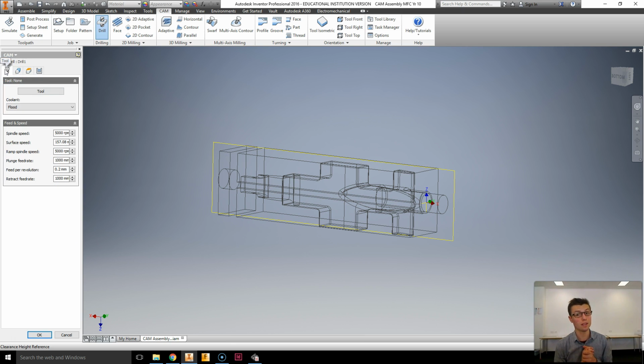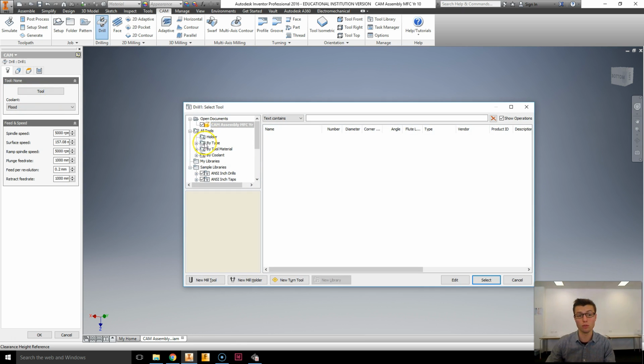Make sure you select the right cutter, everyone. We've got one tool that we use basically for the class subjects of F1 in Schools, and it's a 6mm ball nose, which you need to select and customize for the first time in your computer. It may already be there because another student has done so, but you need to check that they've done it correctly, because if they haven't and you use it, it will not work at all.